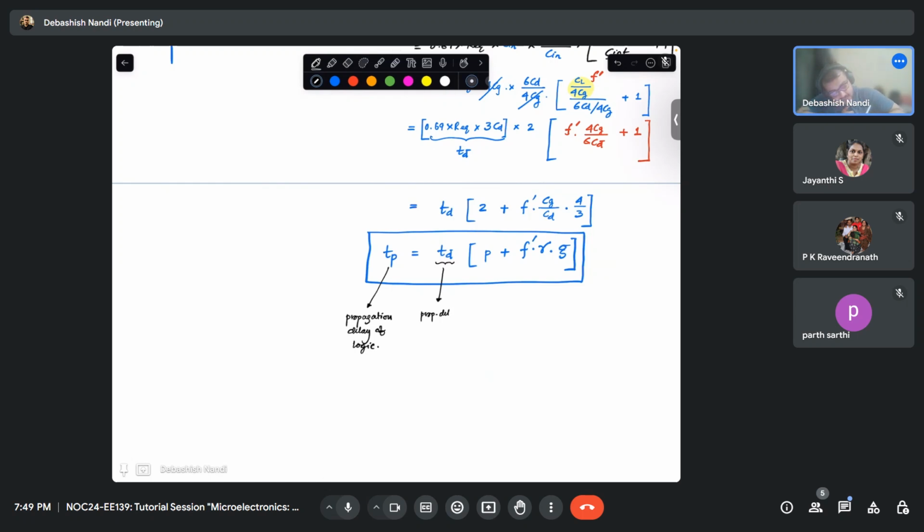It is the propagation delay of an unloaded inverter, or delay unit. What is P? P is basically your parasitic factor.